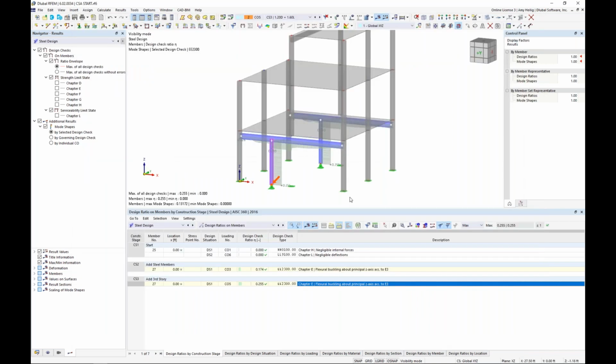Okay, so this will sum up the example today where we have modeled the entire structure. We created those construction stages, not only for the model where we deactivated elements, activated other elements, but also the loading considerations where we need to factor in the construction stages as well to the load combinations and our design situations.